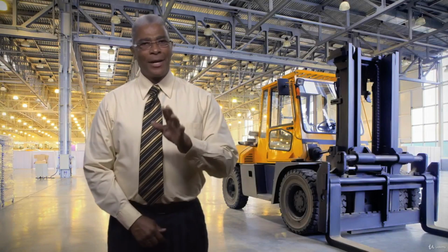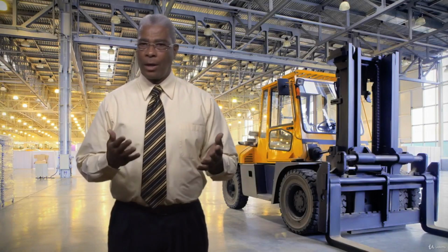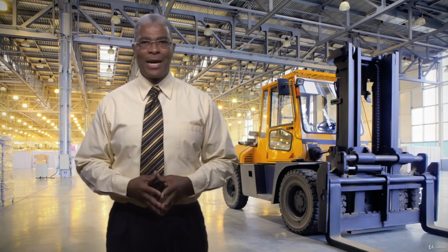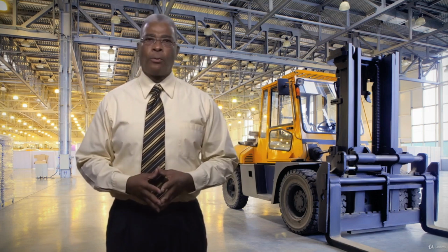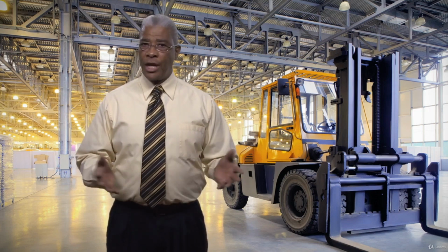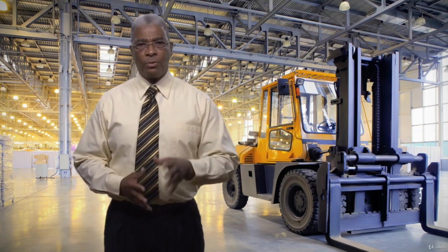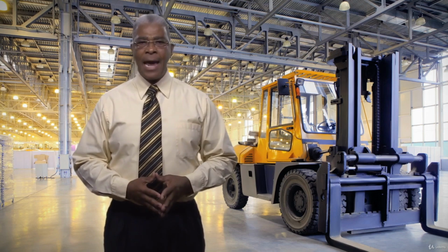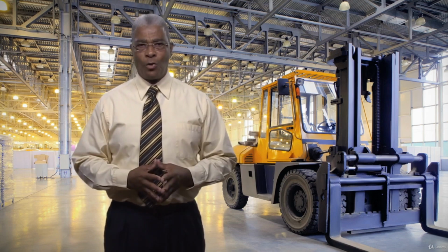Employee retraining is not unusual and is certainly needed in any setting where lockout-tagout techniques are required. There must be retraining with any change in job assignments, change in machines, equipment, or process that presents a new hazard, or a change in energy control procedures. Retraining is also needed when inspection reveals a need, or whenever the employer sees a need, to reestablish proficiency and introduce new or revised control methods.